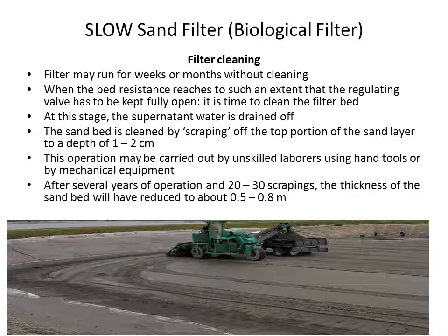After several years of operation, 20 to 30 scrapings would have occurred. The thickness of the sand bed reduces to 0.5 to 0.8 meters, and this is the time to close down the plant and construct a new one.